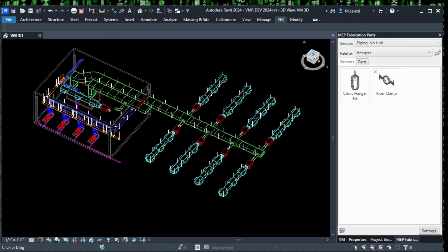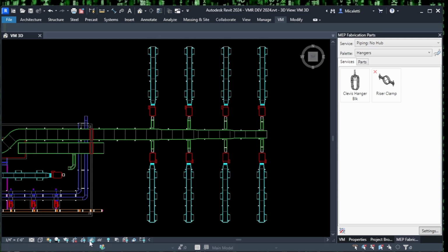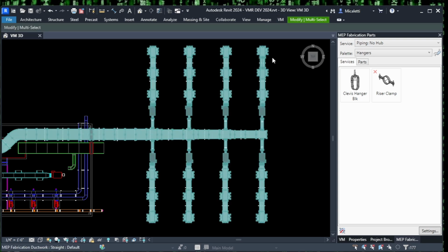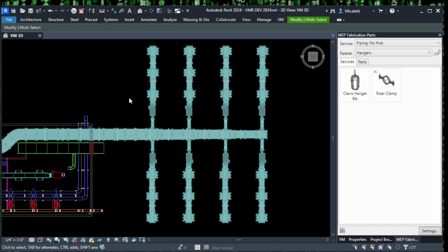And then when you have that set up, you can do something like this. So let's go into this view, and let's lock this. Go ahead and select this whole line here, and we're going to auto tag, which is VAT. So select everything, type VAT. A lot of people are using programmable keyboards and multi-button mice, and you can have buttons for each of these. You don't have to remember the hotkeys. But we'll hit VAT, auto tag this.